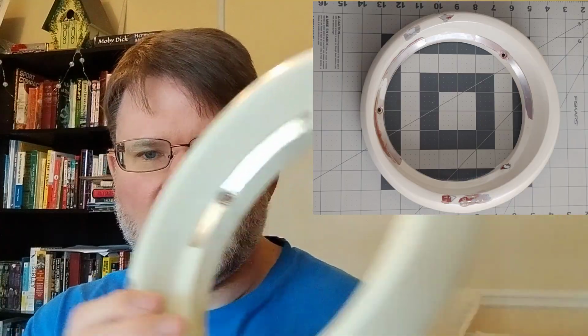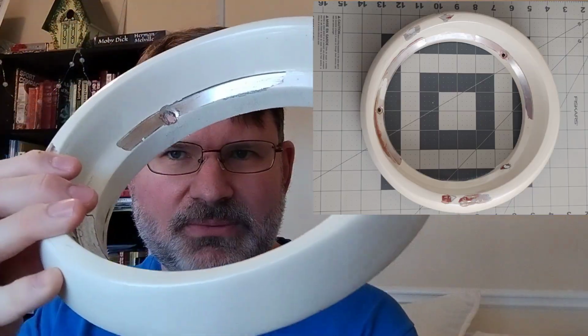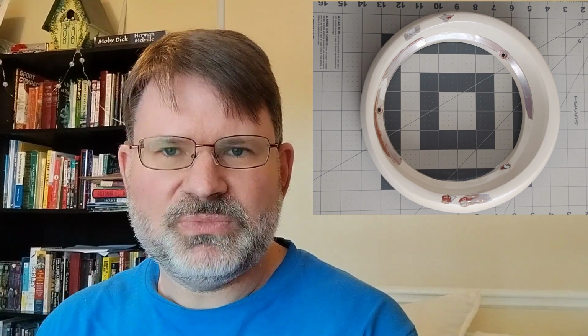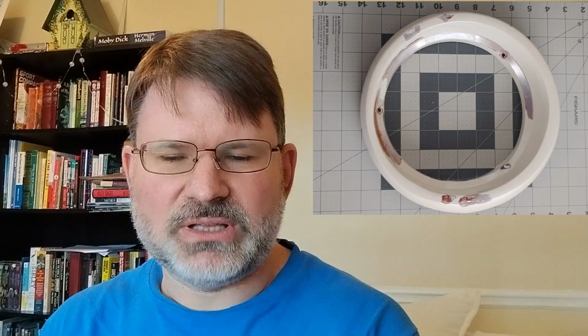Here, you can follow along as I try to use FreeCAD to create a model of this 1964 Dodge Dart headlight rim. The goal with this model is to have something that you can print with a resin printer or laser-sintered nylon, so I can't just make a single block and use a slicer to give it 20% infill. It has to be modeled as a shell with support ribs.